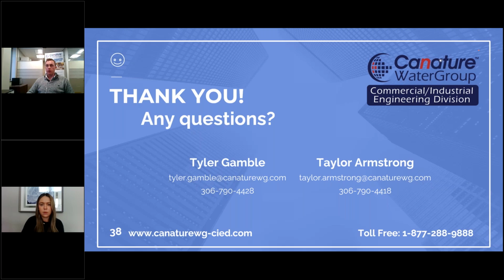Probably the best way to frame it is best practice. I don't know, Taylor, if you agree. Yeah, best practice. The key thing, and this goes for any chemical feed system, make sure it's dosing as often as possible. So borderline continuous, because continuous means that you're probably lacking, but as long as you're continuously dosing, your solution is going to be mixed well. And then try and put that as far upstream from the RO as possible.